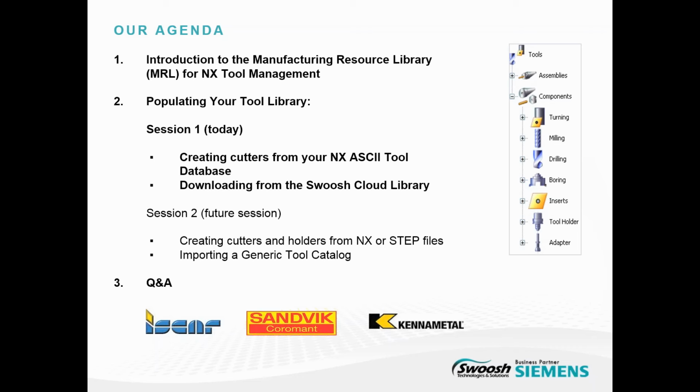But today's focus is going to be on how we would populate your tool library once you actually already have MRL. We've broken this into 2 sessions, and the first session today is primarily working with the NX ASCII tool database and how we can use that to directly create cutters within MRL.